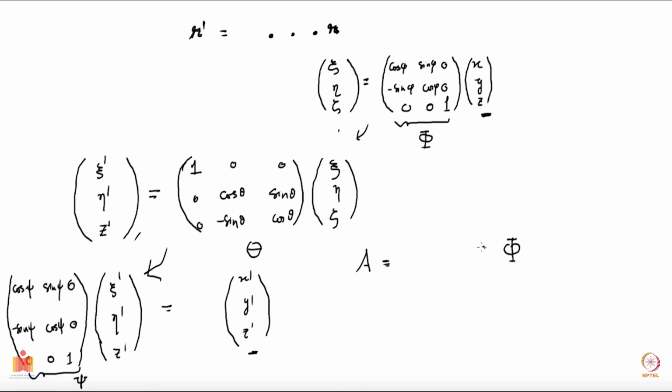And then I have done by theta, and then I have done by psi. Okay, so this is what my transformation matrix A is. So it's straightforward to now determine what this matrix A is by just multiplying these 3 matrices. Okay, and I'll give you the answer for that, and you should multiply that to see whether you also get the right answer. Let me write it down.